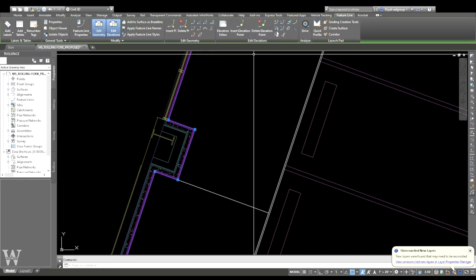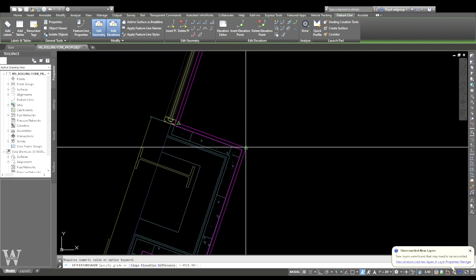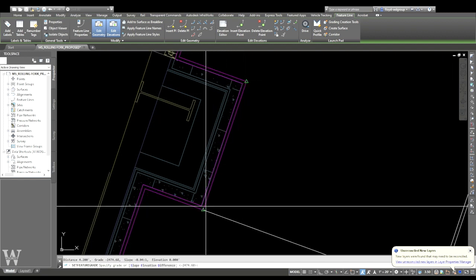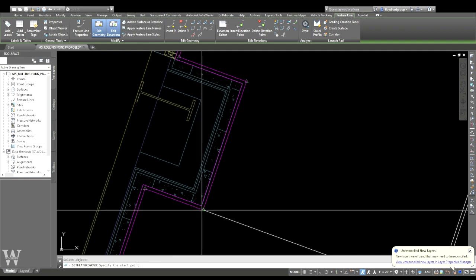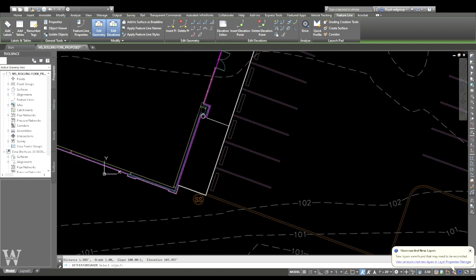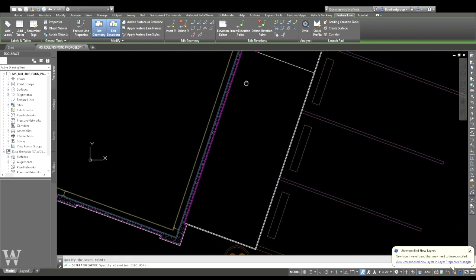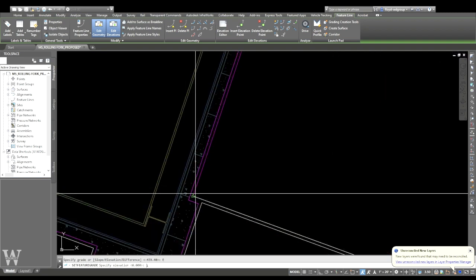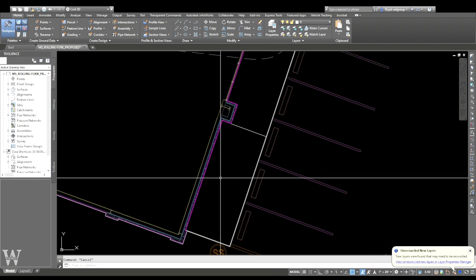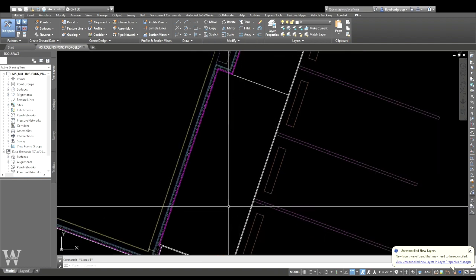So we'll click on this. Grade slope 103.96. Grade minus 1.0. Click here. Grade 0. Click right here. Grade 1.0. And then go from here to here to elevation 103.90. Okay, that gets us to there. Now we can work our sidewalk around right there.